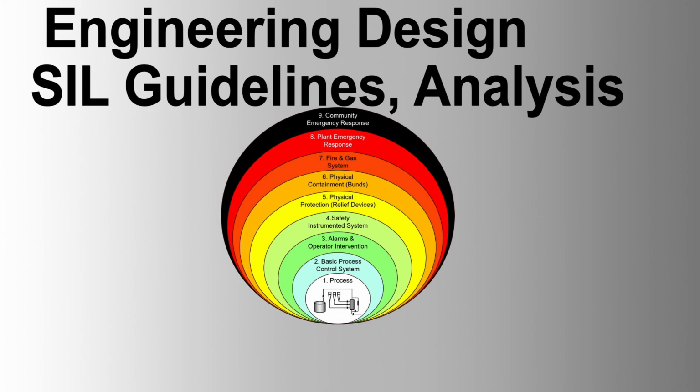Warnings. 1. FTA cannot account for all possible failure pathways and relies on the analyst's identification of these paths. 2. It is not a substitute for good engineering design principles, but a tool to assess the SIL of the SIS design. 3. Different methodologies like FTA and Markov modeling may yield different results due to their inherent mathematical approaches.